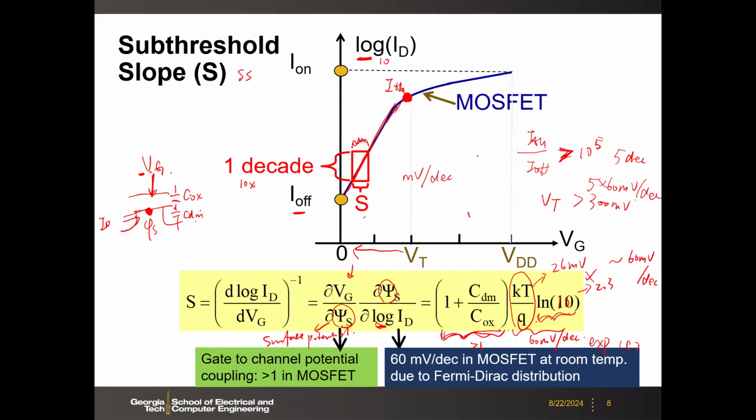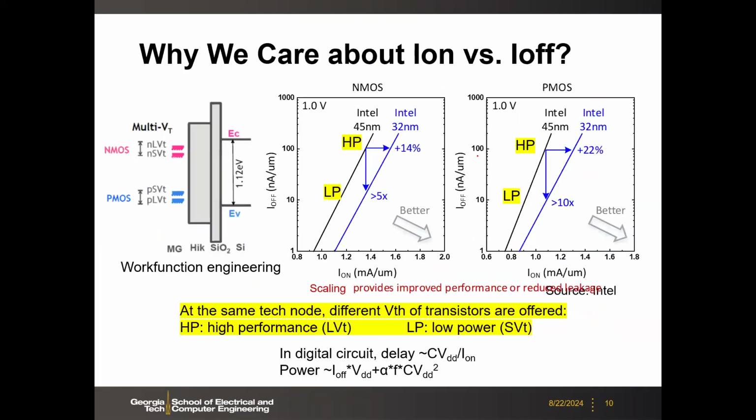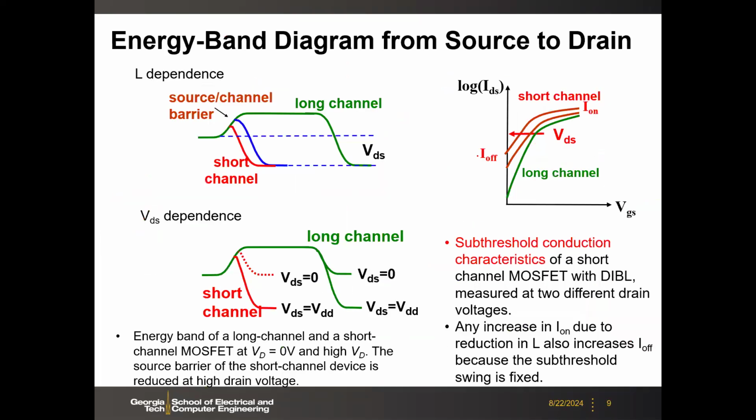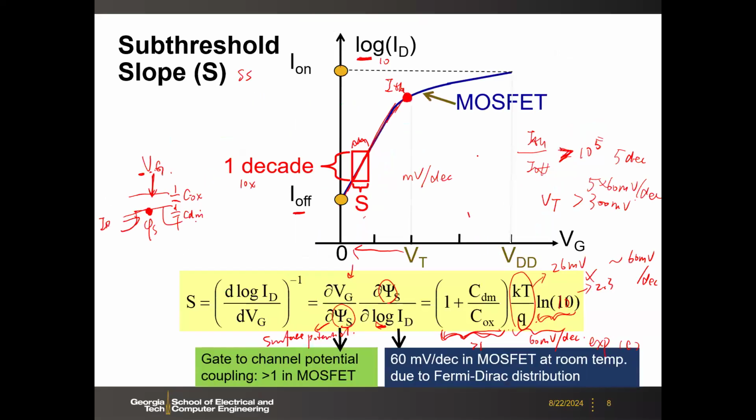So any questions? So today's transistor threshold, 300 millivolts, 400 millivolts. And then your VDD, your power supply, needs to be larger than that. That's why the lowest VDD you can get is about 600 millivolts today. Okay. So let's continue.